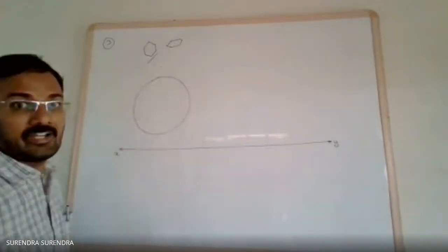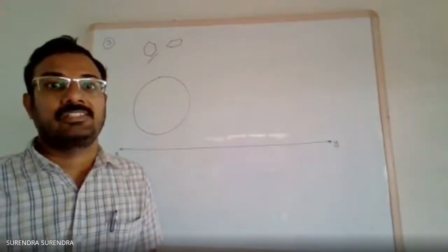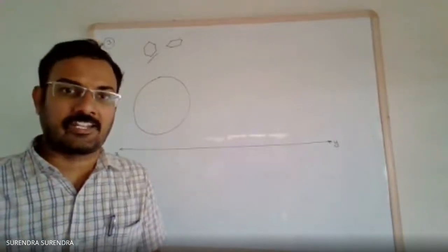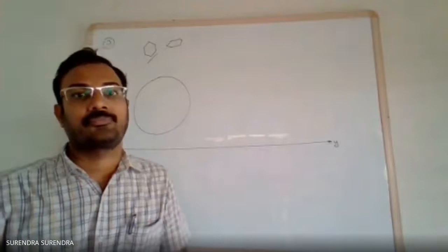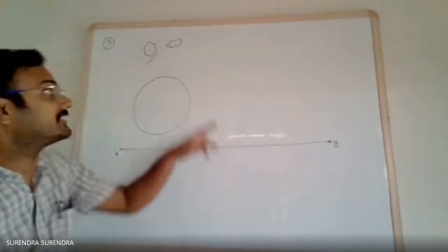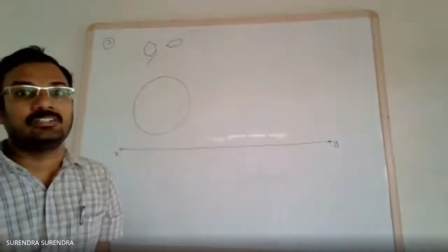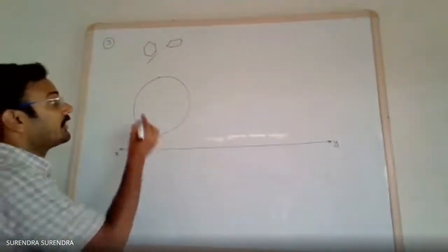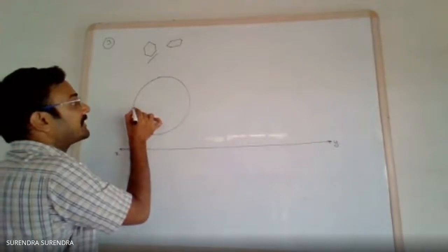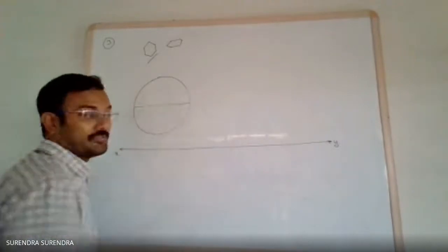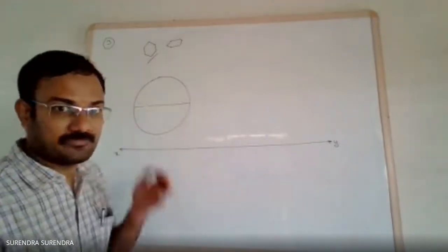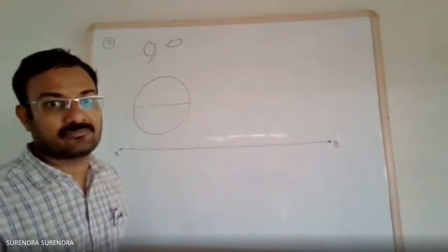With 25 mm radius, draw a circle with 2H pencil as light as possible. Now, as we require the hexagon in this orientation with two of its sides parallel to the XY line, draw a horizontal diameter line. This is also with 2H as light as possible. No need to show this line.